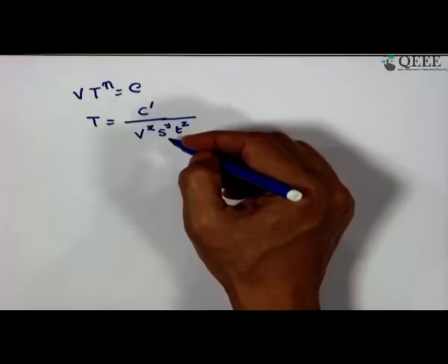So, that is why we see the depth of cut in that way does not affect the tool life or the cutting temperature. Rather, if we increase the T by S ratio, that means compared to the feed, if we increase the depth of cut, in that case we can bring down the cutting temperature in a very positive way, and that has a favorable effect on the life of the tool.